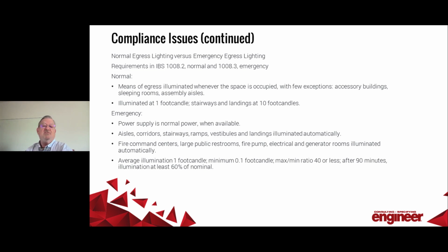Nobody wants the lights on while they're sleeping, or in assembly occupancy. The requirements aren't so restrictive. The minimum illumination is 1 foot candle, with 10 foot candles required in stairways.